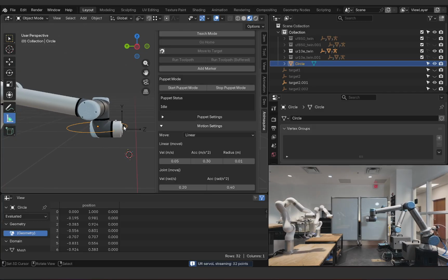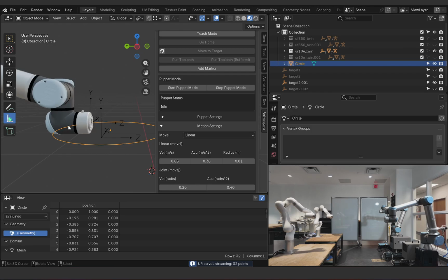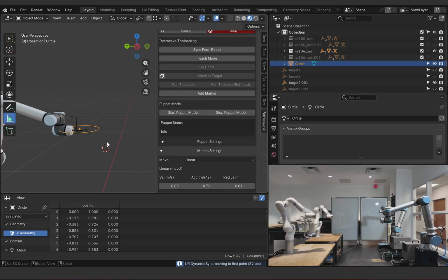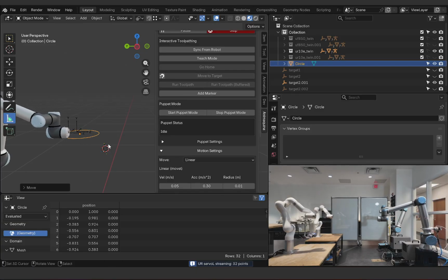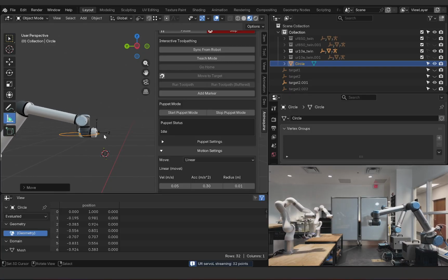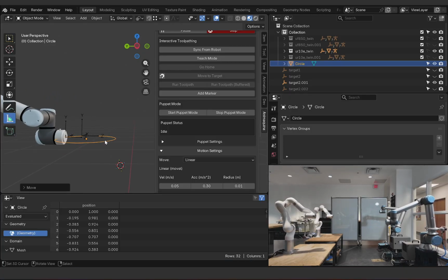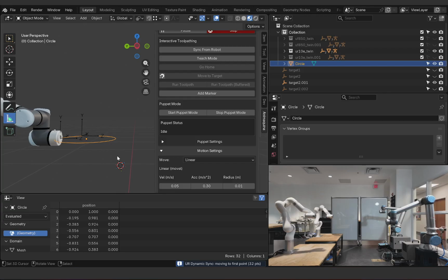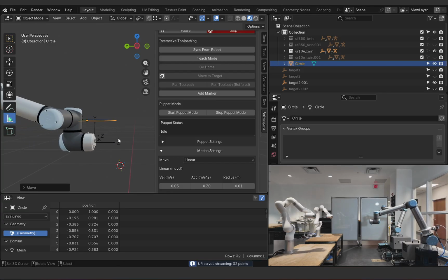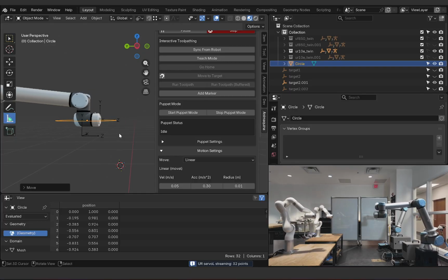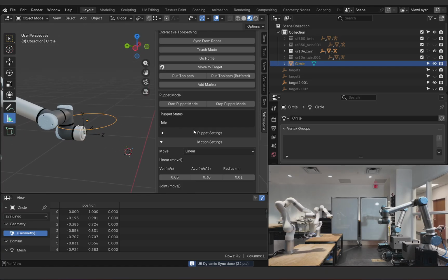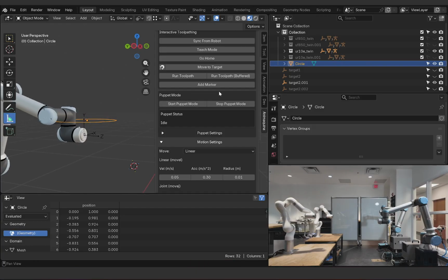There you go. So now, as it's performing the points, we're actually buffering some points. So I'm going to send it one more time, and then I'm going to update the path as it's going. So you should see after the buffer has run, the robot will correct to that path. So again, that's an option that you have in case you want to add some activity to your toolpath. That is possible.